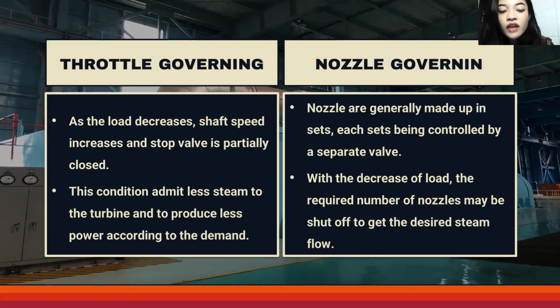Number 2, nozzle governing. Nozzles are generally made up in groups. Each group is controlled by a separate valve. With the decrease of load, the required number of nozzles may be shut off to get the desired steam flow.